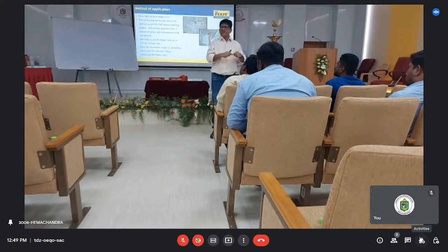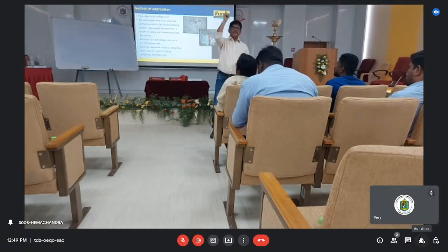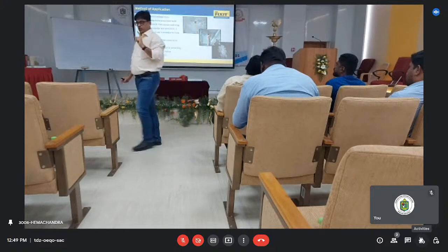Now, with normal grout for void filling, you can have a center to center spacing of around 300 mm also. But in case of active leakage, you may have to do it with 50 mm or 75 mm depending on the situation. So when it is active, you have to be closer.